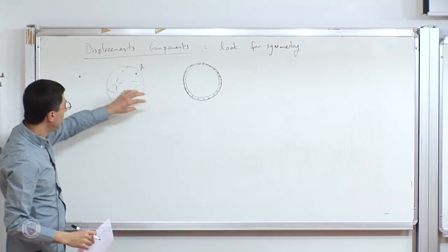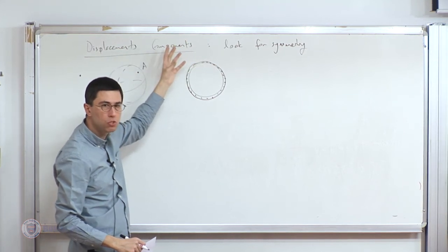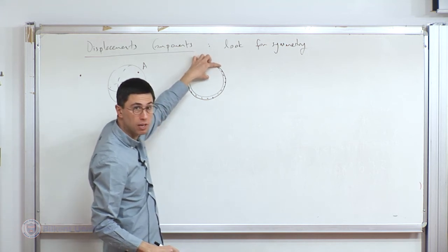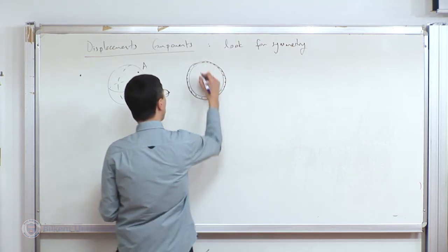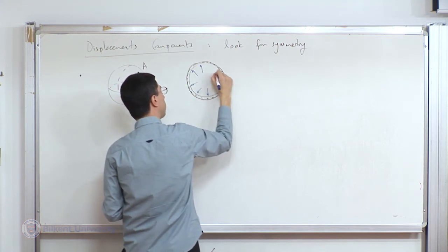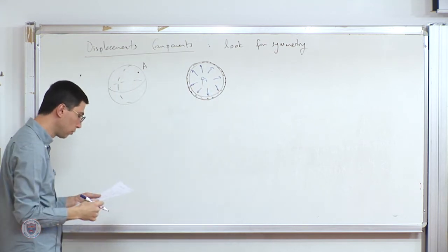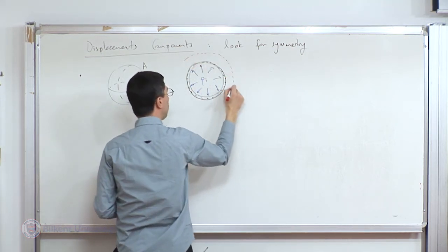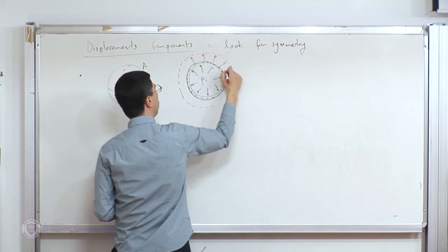So this sphere is actually hollow, and it has some wall thickness. This wall thickness may or may not be small. And in fact, in this course, we're going to look at the case where the wall can be rather thick. Okay? That's something that we have not talked about before. In 232, we looked at the thin wall case. In this course, we will be able to look at the thick walled case. So there is some internal pressure. You pump air into it. And the deformation field is such that, and that's what we need to visualize, the deformation field will be outwards.